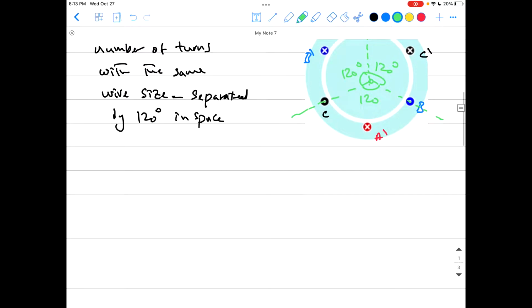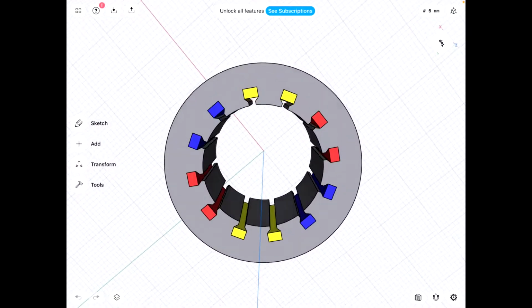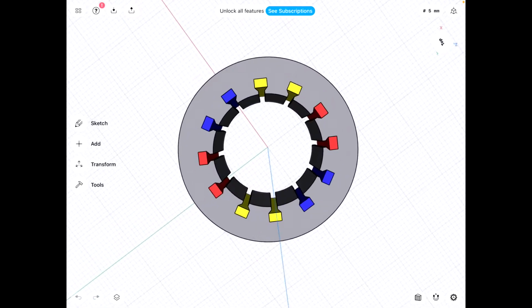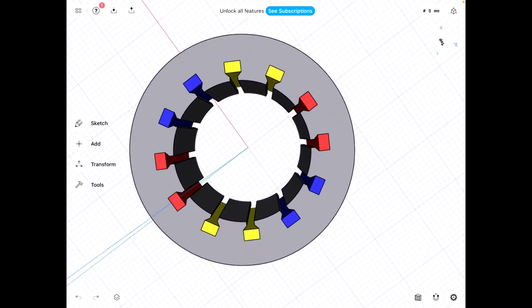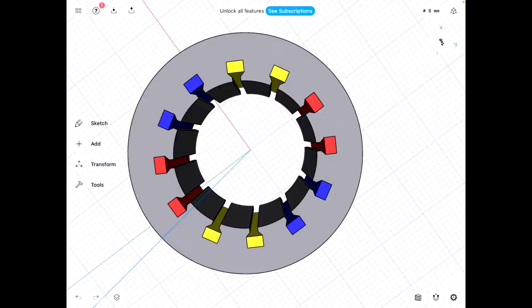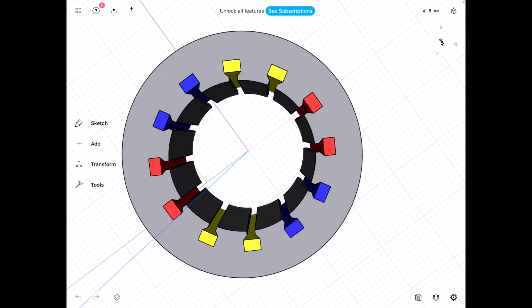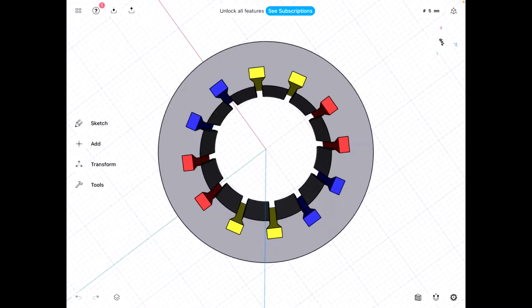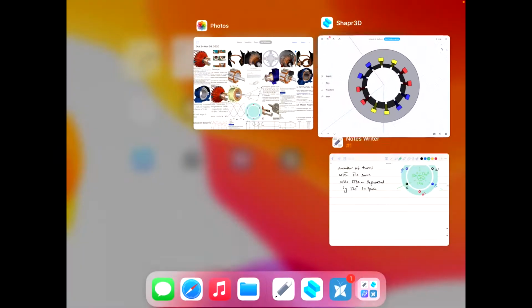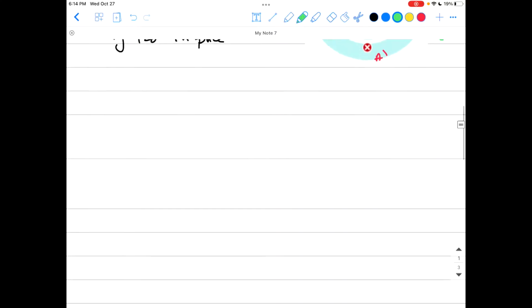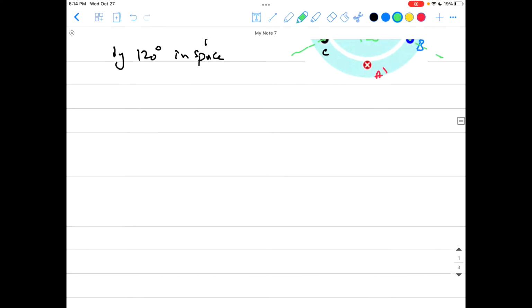How do you do this? It's just like we saw here in some more realistic stator. In the other photo we just used one slot to represent this. It's a design parameter, so it doesn't matter, but for now, you see it is just three typical windings, evenly separated around the circumference of the stator. That means they are just 120 degrees apart from each one. That's what makes them balanced three-phase winding, and they have to be balanced to achieve the required performance of this kind of motor.